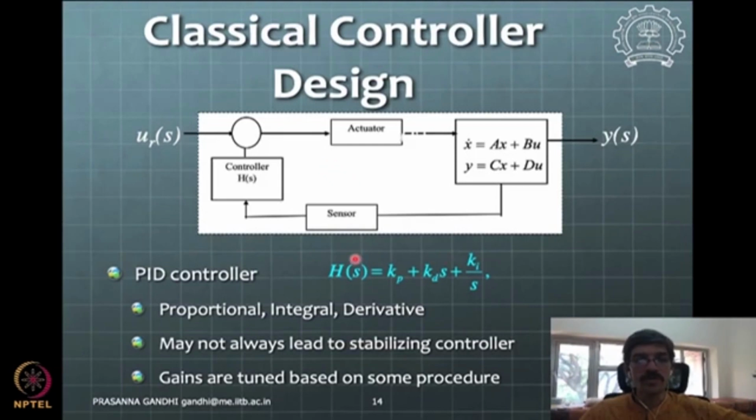typically you will avoid carrying out pole zero cancellations by using a controller. Okay, as some part we know, if we cancel the poles, especially in the left half of the plane, this cancellation is not really going to be exact, because the actual system and its model will always have some small differences here and there, and then only that small part which is not compensated completely will have some undesired effect on the system, and it may not work well. So that's why, from that perspective, we don't do the cancellations here.